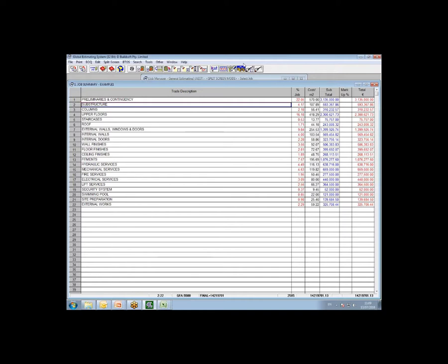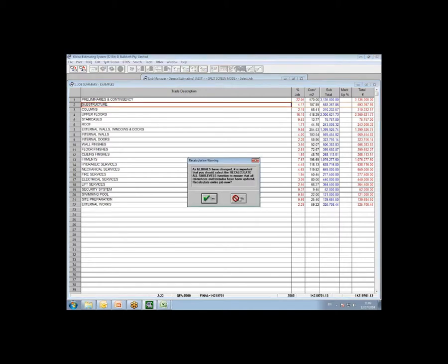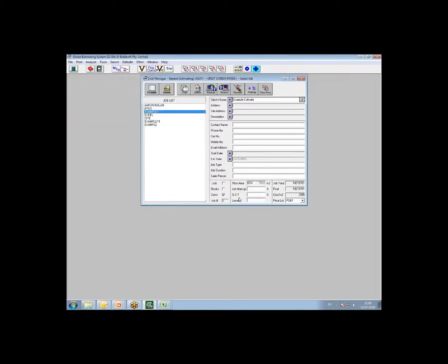Okay, so that's your Excel and PDF export. The next format that sometimes you might need to export out to is called CITE. CITE stands for Construction Industry Tendering Electronically. It was designed by a coalition of people so that different systems, specialist systems like Buildsoft and any other application, can transfer from one to another. And it's probably the easiest method to export and import into Buildsoft because it's custom made for systems such as ourselves.